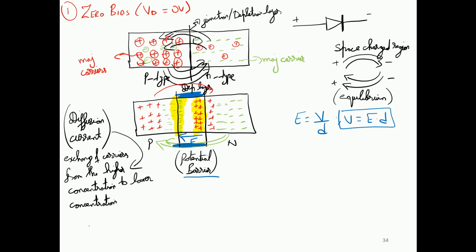So this can be termed as a definition of a diffusion current, when the charges move from the higher concentration to a lower concentration, and thus an electric field is produced inside the depletion layer, which we call a potential barrier, and thus no remaining charges from the positive side can go to the negative side and vice versa. So this is the scenario which happens when we consider a no biasing state, or the natural state when n type and p type materials are combined together. So this was the first scenario.